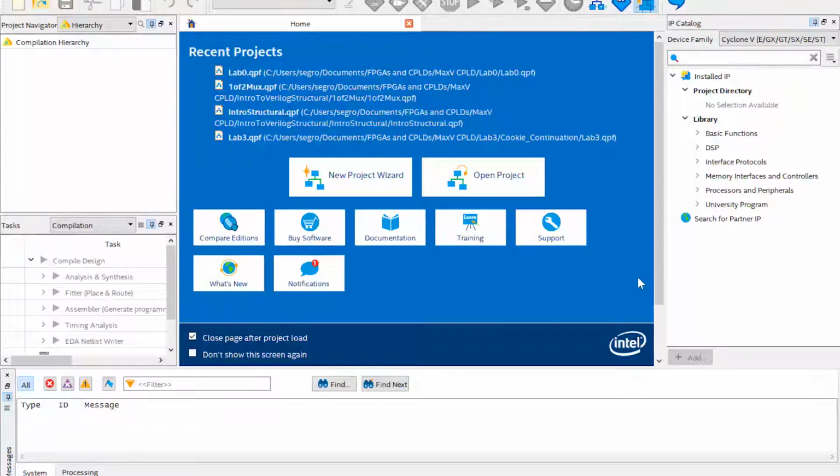For example, I'm looking at page 8, we've got PB0 as the push button. That's actually what's written on the board itself. If you look on the circuit board, you can see PB0, PB1, et cetera. So when you want to use that physical switch that's labeled PB0, in the software you'll reference pin_52. That's fairly obvious, but I think that should make sense.